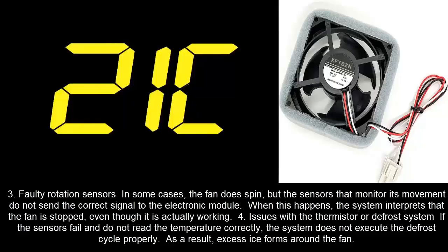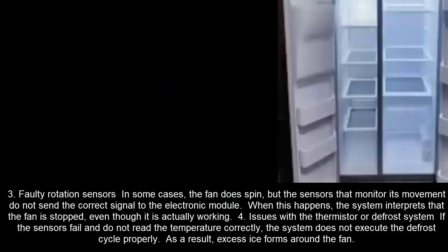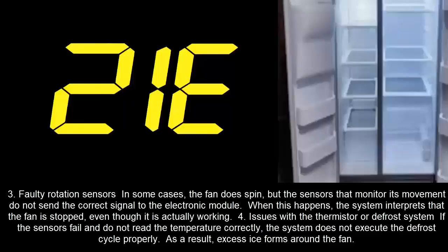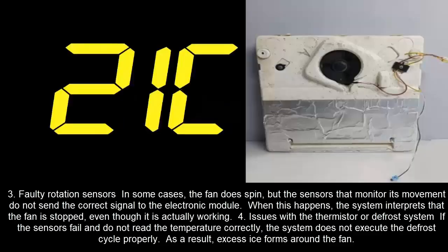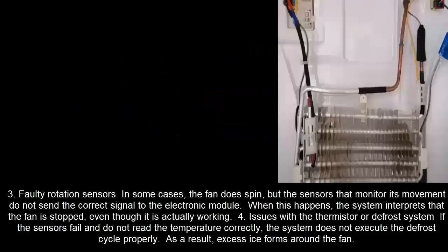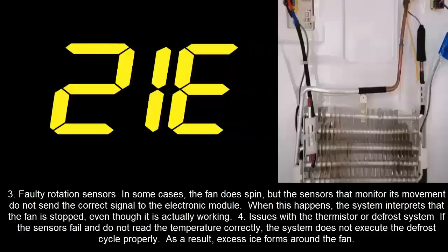3. Faulty rotation sensors. In some cases, the fan does spin, but the sensors that monitor its movement do not send the correct signal to the electronic module. When this happens, the system interprets that the fan is stopped, even though it is actually working.